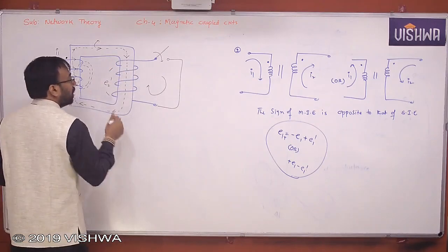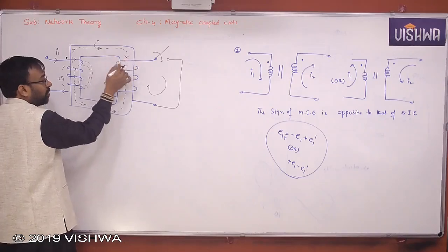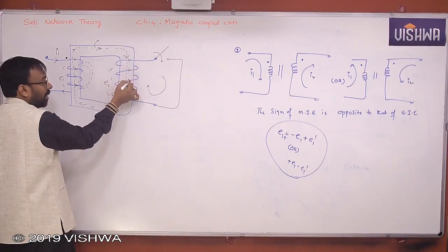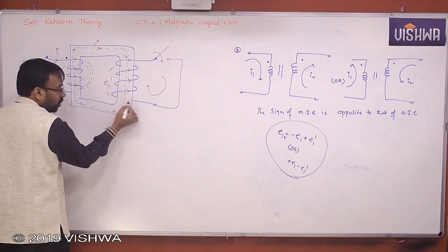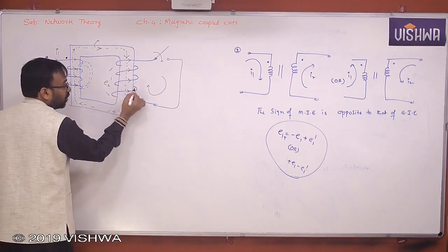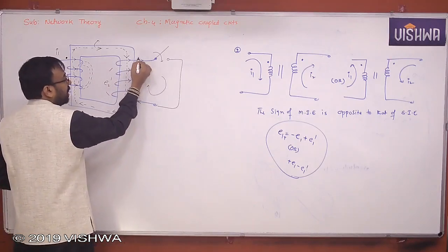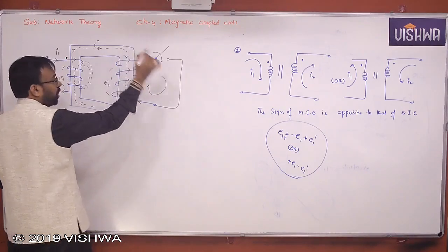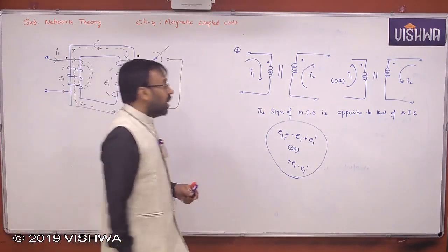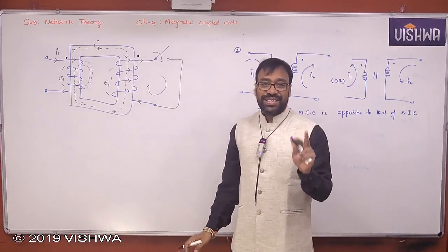It is simple. You're holding the coil like this. The upper portion of the coil you are able to see like this. Now obviously the current is flowing like this, which means it should come from here, then only it is possible. That's it. This is leaving. And identify the terminal where the current leaves and put a dot there. The whole story, what we have implemented, is just to identify the dots.